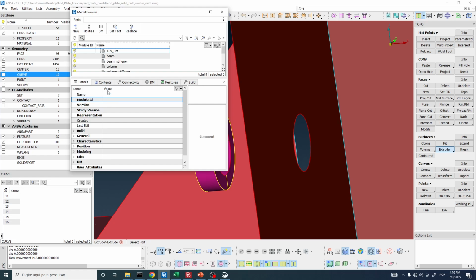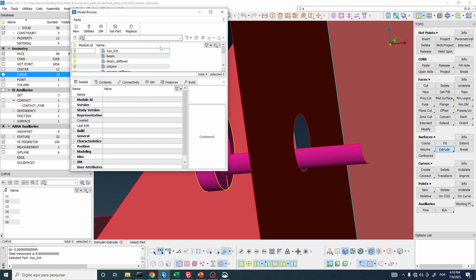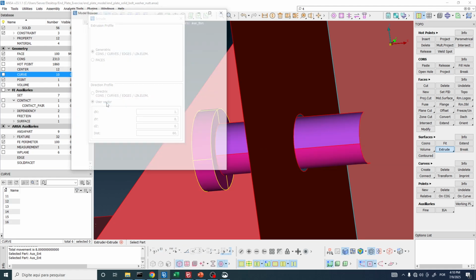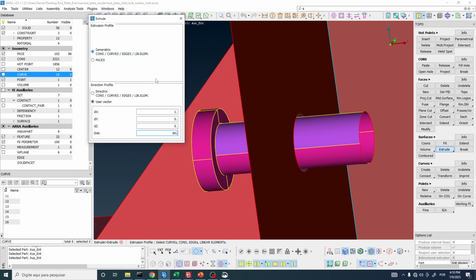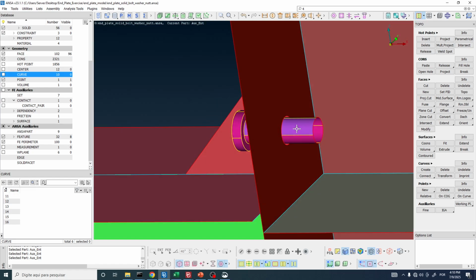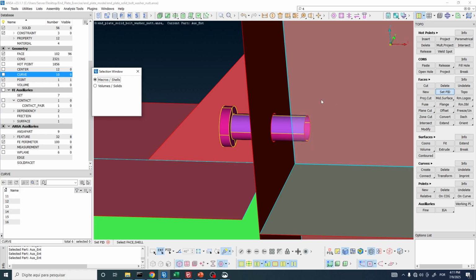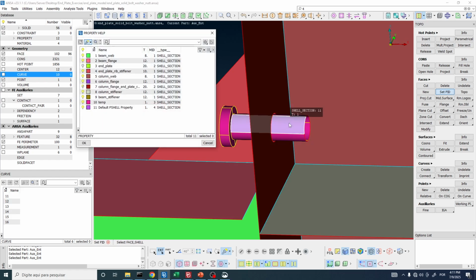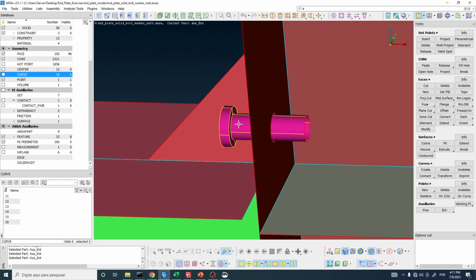Select the temporary property, auxiliary entities, close. Oh God, it's creating one by one. So auxiliary entities and temp, auxiliary entities and temp, and again. One of these faces was assigned to a different property, this one with a different color. So let me use the setPID function, select this face, middle mouse button, and I want to assign this property. So select this other face, which is the temp property, middle mouse button. Okay.